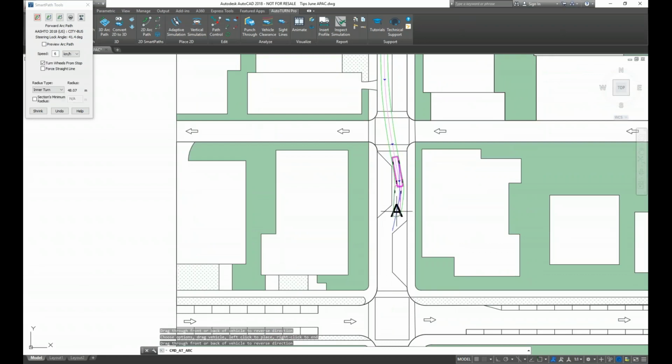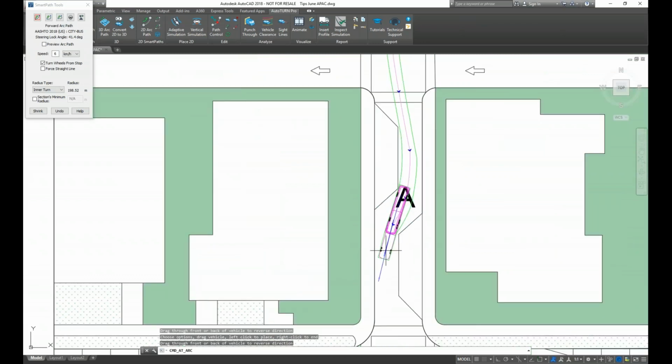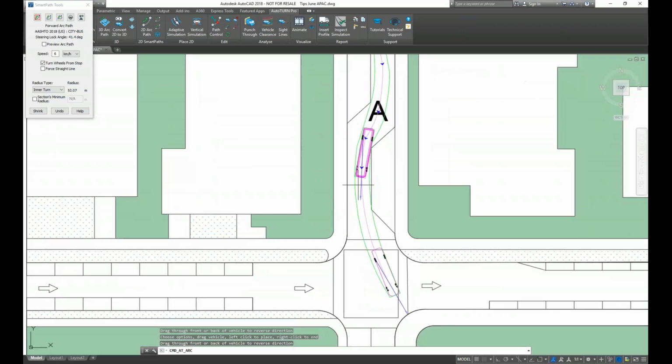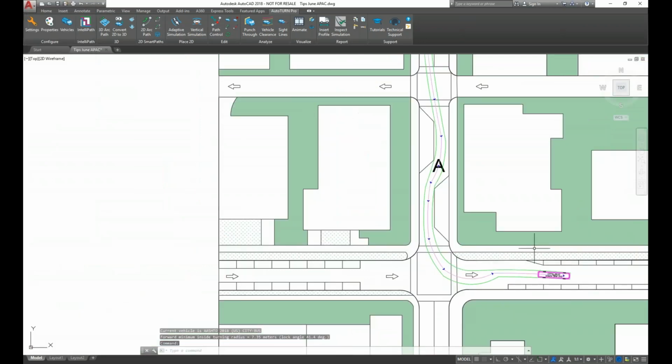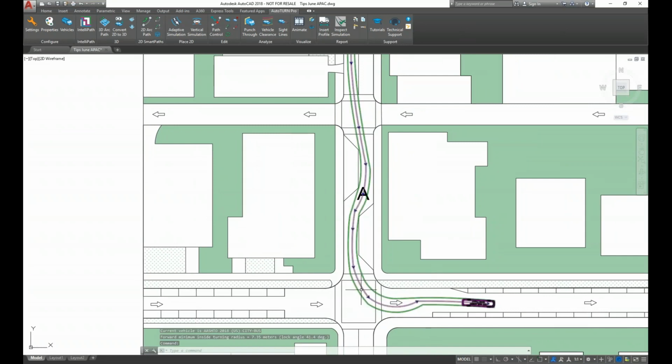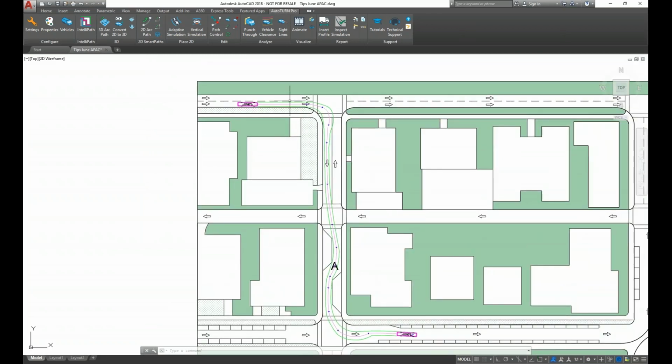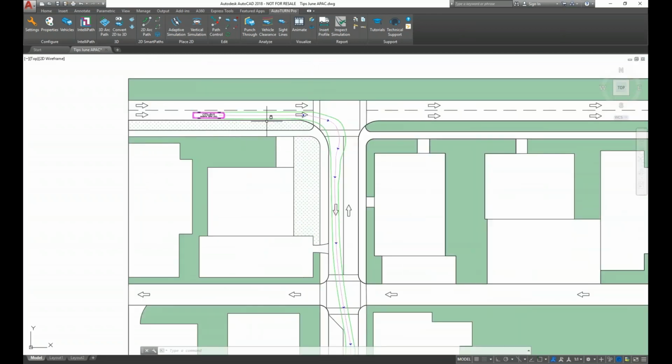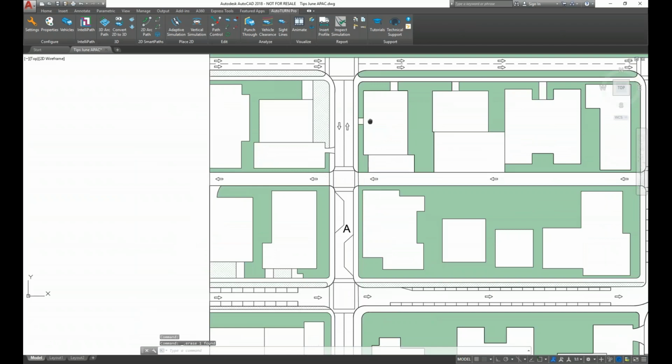This process might take a bit longer, where you have to check all the constraints, see the turning characteristics, check the speed, and see that the vehicle body doesn't encroach into any other space. This would be the typical maneuver which we have to check. You can see that there are multiple picking points or stoppage points. And in our previous webinar, we saw that when the number of sections is increased, the simulation may not be the perfect one. So what can we do to avoid these situations?